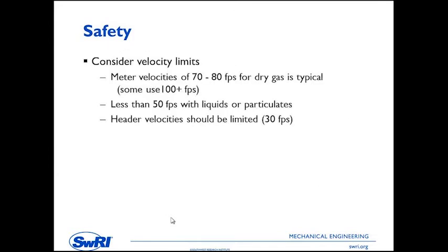Typically, meter stations are designed to a 0.5 design factor. And if the facility is located in a Class 4 location, design classes being defined by the number of houses, residences, or large population facilities located within a close proximity of the pipeline, you would derate to 40%.